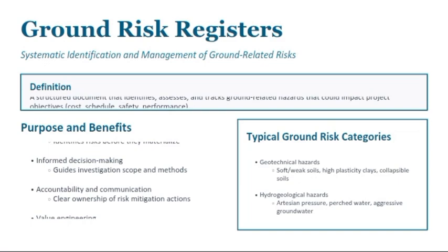Now the typical risks recorded include soft ground, differential settlements, high groundwater table, contaminated soil, cavities, liquefaction, slope instability, expansive clay, and rock fracturing. Now I just said that all together, but actually it has a category. It's categorized into structural risk, into geotechnical risk, and contamination risk and the rest.